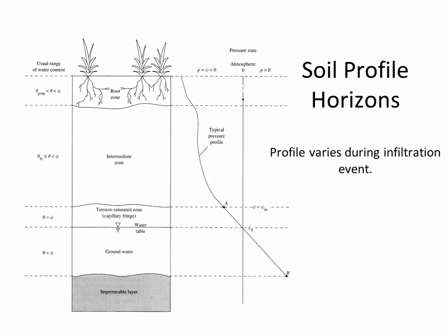Now, above the saturated zone, they call this the capillary fringe. And the water content is elevated in that zone because this is the zone that actually the soil is able to suck water up from the zone of saturation. Now, there's going to be some large voids where there isn't enough tension to fill the large voids entirely.